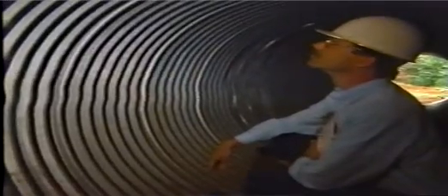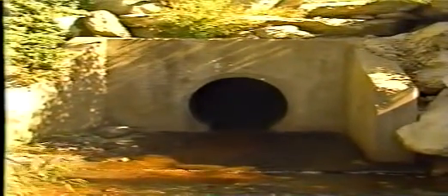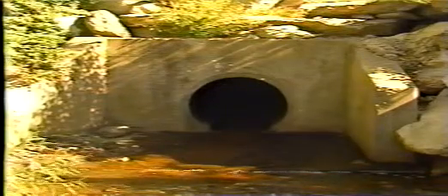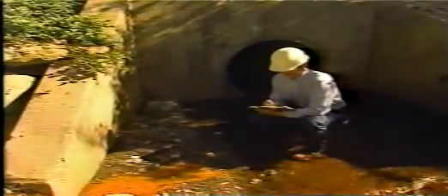Metal conduits are susceptible to corrosion, rust, scaling, flaking, and pitting, especially if the paint or protective coating is damaged. And as mentioned earlier, cavitation and erosion damage may occur. Be alert for seepage that may be flowing into a conduit through joints or cracks. Continued flow from a conduit after a non-leaking upstream gate has been closed is evidence of seepage into the conduit. Check for any soil particles that may have been piped into the conduit. If you see seepage exiting from around a conduit at the downstream end, it should be considered a serious situation. Alert an engineer immediately.